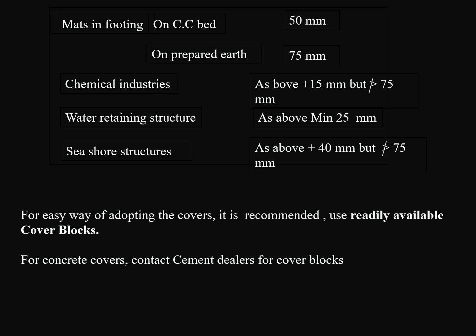For chemical industries, as the above mentioned cover, minimum cover should be added with 15 mm but should not be more than 75 mm. Water retaining structures as above, subject to minimum of 25 mm. Seashore structures as above plus 40 mm but should not be more than 75 mm as per IS 456.